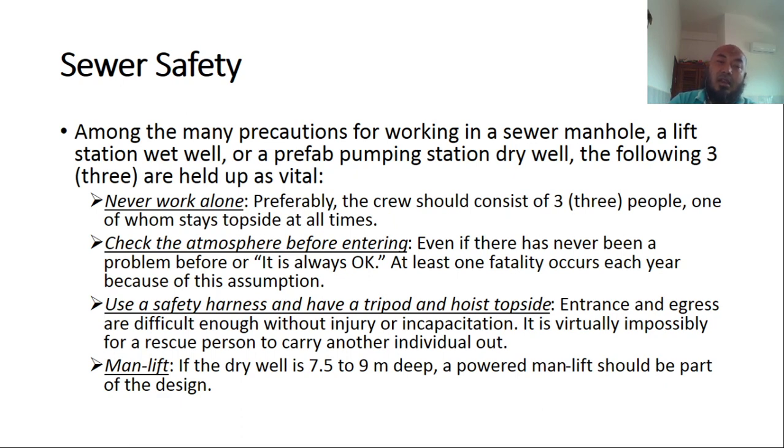Number three, use a safety harness and have a tripod and hose topside. Entrance and egress are difficult enough without injury or incapacitation.